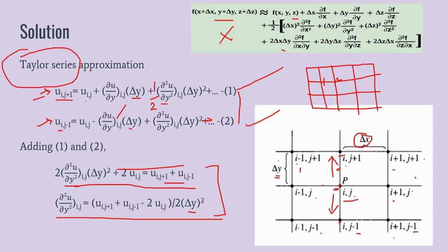Suppose it is in a triangular duct or some irregular shape, there this delta x and delta y, and also this equally spaced grid points won't be there. So this delta x and delta y will be varying, or also if there is delta z in a three-dimensional case, all these quantities will be varying.